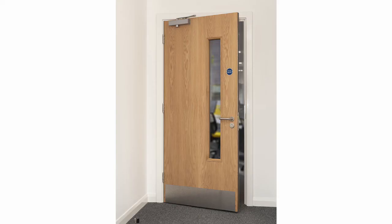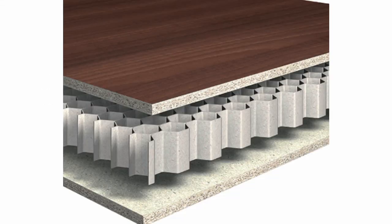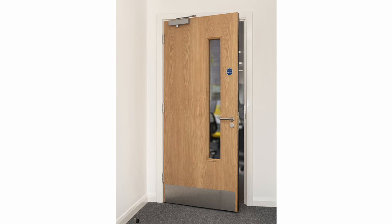Because of the weight of a fire door and to prevent it warping, fire doors are usually fitted with 3 fire door hinges. Hollow flush doors using egg box or similar construction will not be fire doors. This can be detected by the weight of the door because fire doors are much heavier than a hollow door. To check the weight of a door, instead of removing it, you can detach the self-closer and swing the door between your thumb and index finger. This gives a good indication of the weight of the door. Hollow doors are reasonably easy to detect using this method.